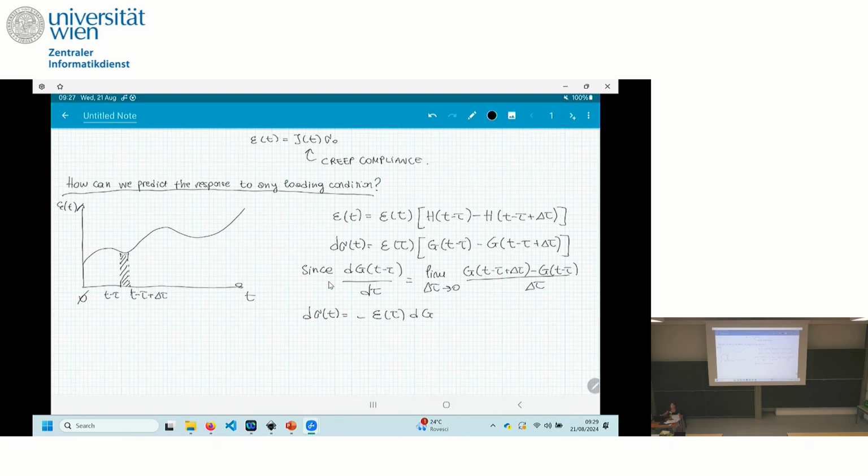So in that one, you need to do some fixing. The Kelvin-Voigt model is going to be problematic in the relaxation because of that problem. But there are ways, numerically, to fix it. It's not perfect.